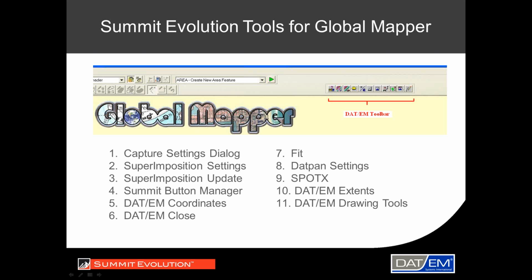But you might want to, for example, place spot elevations with Summit Evolution, because you can set that cursor on the ground and digitize the spot elevation in 3D. So you would use the datum spotx command to do that. Wherever datum has determined that we need a 3D command, we've added that for you to go ahead and digitize in 3D.